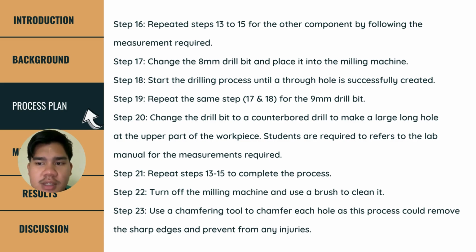Turn off the milling machine and use a brush to clean it. And lastly, use a chamfering tool to chamfer each hole, as this process could remove the sharp edges and prevent any injuries. That's all from me.